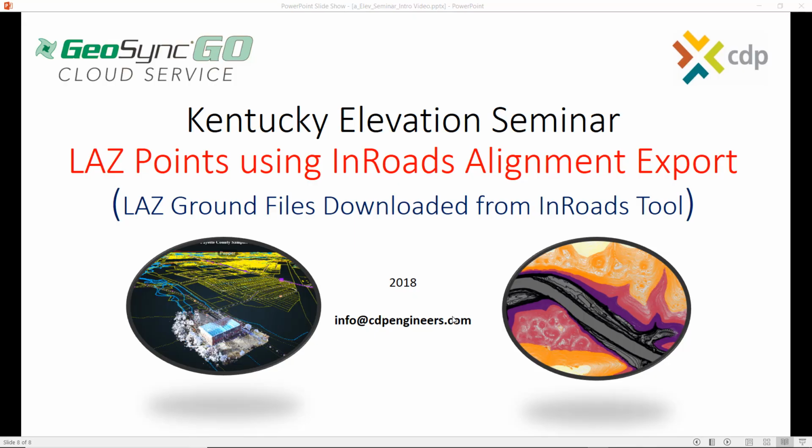This video will demonstrate how to use an InRoads alignment export, a DXF centerline file, to extract LAZ points for use in creating a terrain. In this case, the LAZ ground files were already downloaded using the existing Kentucky InRoads tool.